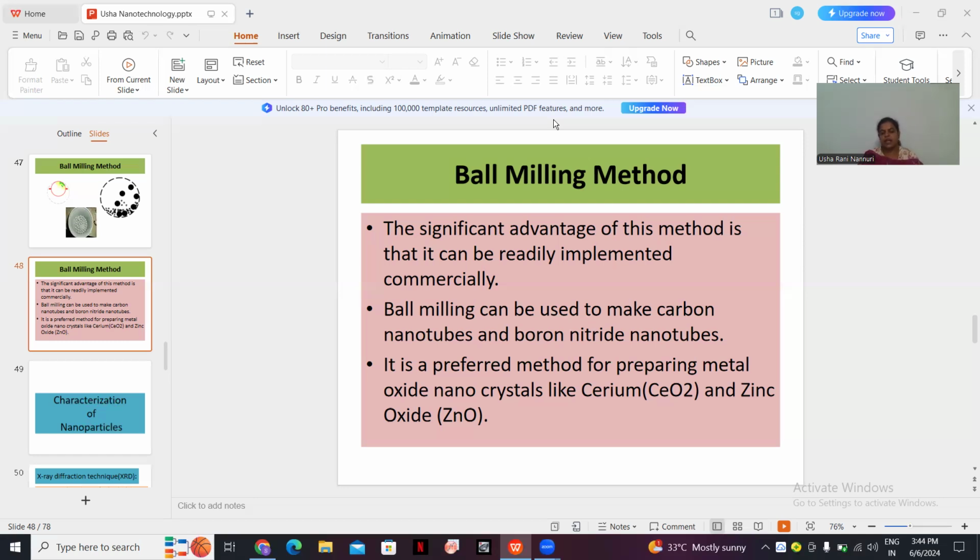The oxidizer can be any metal nitrate, and the reducing agent may be an organic fuel such as glycine, oxalic acid, urea, hexamine, sugar, ethylenediaminetetraacetic acid, etc. Metal nitrate plus fuel finally gives nano metal oxides plus gases. In order to calculate the fuel quantity, the total oxidizing valency of the metal nitrate must match the total reducing valency of the fuel.